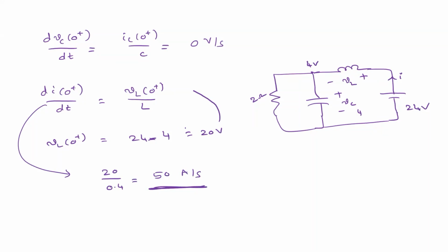Right. So here we have to use our simple techniques, either KVL, KCL, node voltage method, loop current method, or by observation. So we need to find out these values. There are no standard methods, so the method will vary from circuit to circuit. Most of the cases, either KCL or KVL will work out. But you need to properly analyze the circuit and properly identify the current directions or voltage directions, right? I will give you one example.